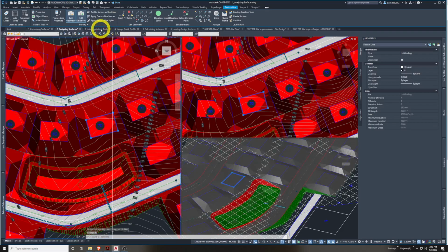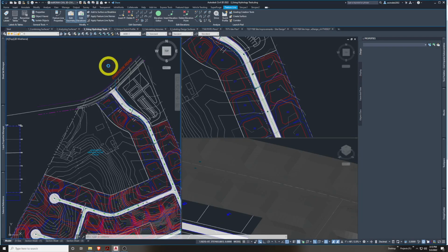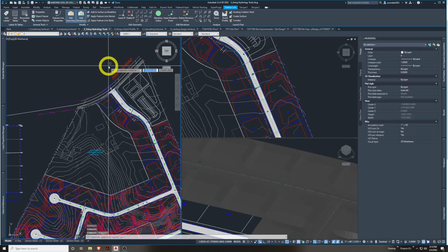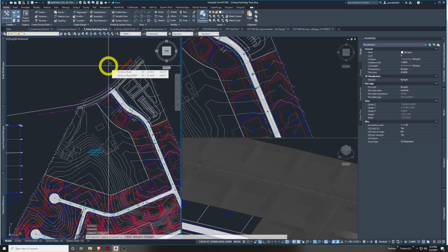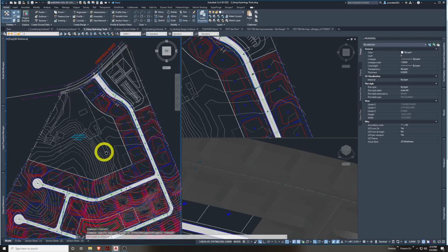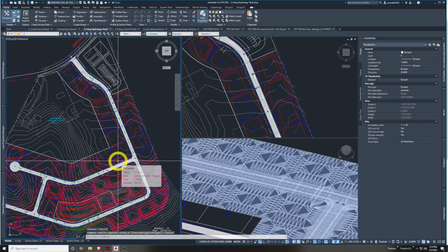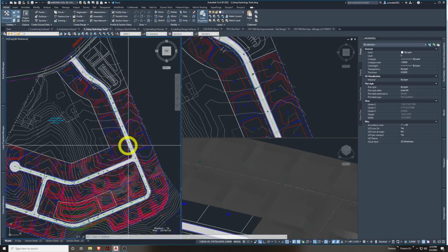So I'm going to go on to the third file. We're going to learn a little bit about some hydrology tools. Mainly, as we learned about watersheds, we're going to learn about catchments. A catchment is an area that shows, if you pick a point on a drawing, exactly what theoretical area all around it is its catchment, or what total 2D area could drain to that point you select. So it helps us fine-tune drainage of a site, and it also helps us to see what kind of area is going to flow into it theoretically based on our beautiful survey map or design map.